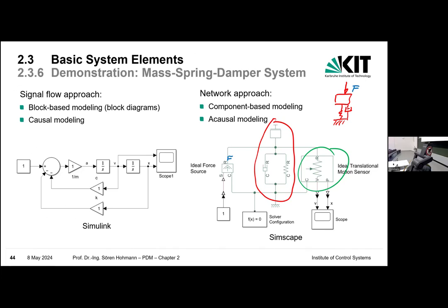You should know a hybrid car has a combustion engine and an electrical drive, and you can combine the electrical drive very differently with the combustion engine. You can make a serial connection, like in a train. You have a combustion engine which drives a generator, it generates electrical power. This electrical power is then used for an electrical drive, serial connection.